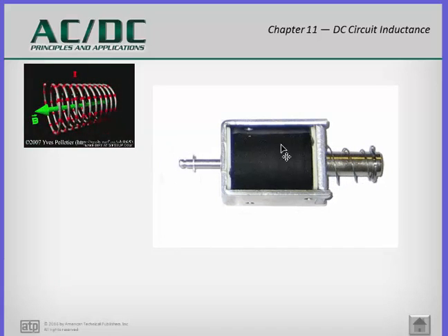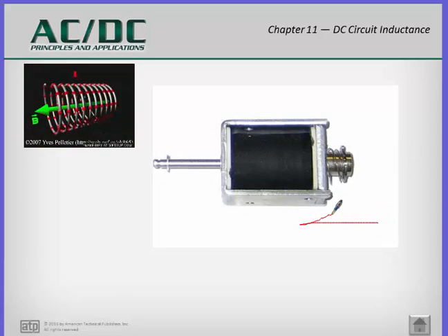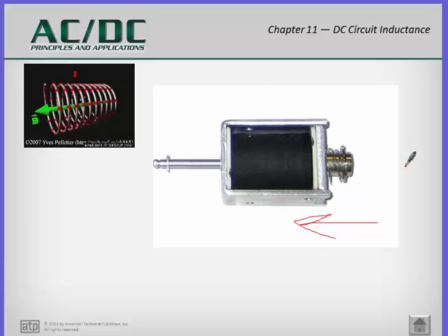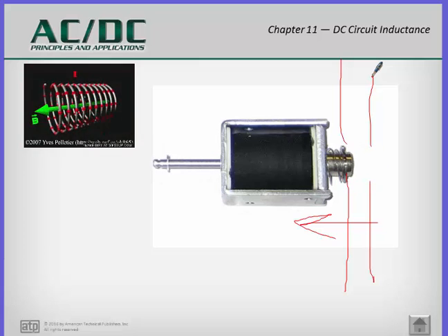So in this instance the electricity is on. It pulls the plunger towards the coil. It pulls the plunger in like this. When the electricity is removed, though, this spring right here forces the plunger back down. So if our pipe was here, obviously the water could not flow through when the plunger's down. It could only flow through when the plunger's up. Our process may be something other than water. Obviously it could be anything. We'll call it our process. Our process could flow through when it was up. Spring-loaded mechanical energy makes it go back down.